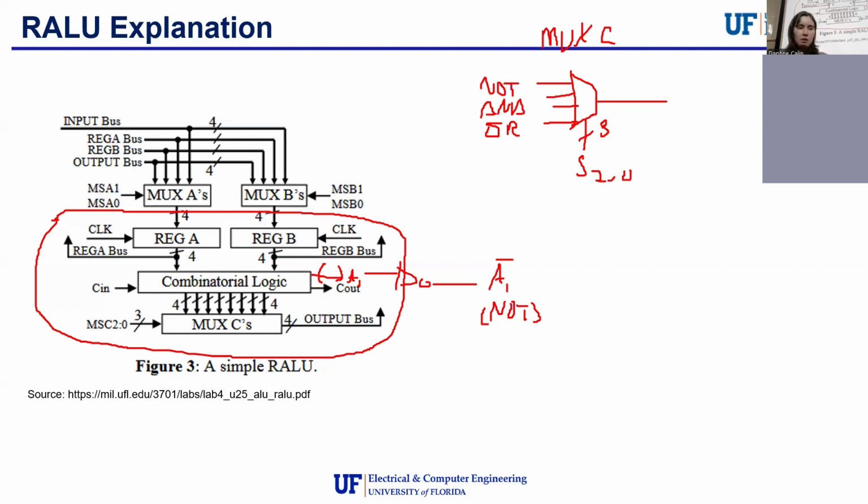And each register is literally just a collection of D flip-flops. In this case, we have 4 things in the register, so we need 4 individual flip-flops, one for each bit. My point is that you've already designed how the ALU works. You might have to expand it to implement more functions with the bigger mux, but when you get to the RALU, you've already designed the ALU part.